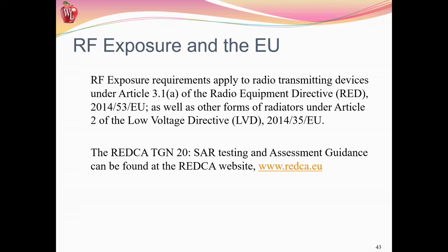The RED CA has a TGN, or technical guidance note, for SAR testing and assessment guidance. You can go to the RED CA's website, find that guidance note, and follow it to determine how you would show compliance with the requirements for the Radio Equipment Directive and possibly the Low Voltage Directive, which also touches on RF exposure for safety.